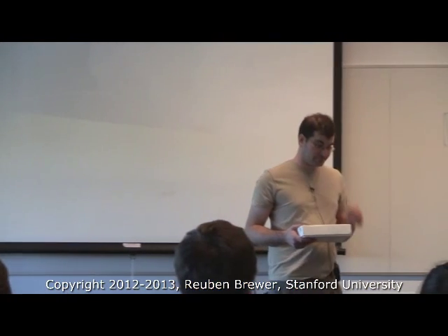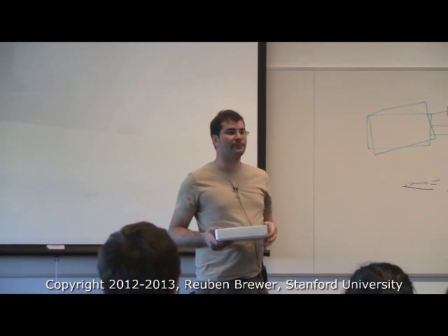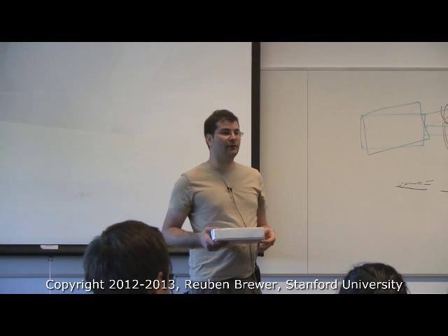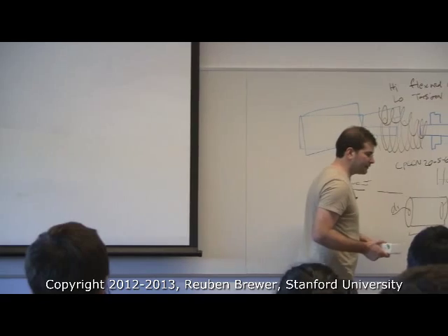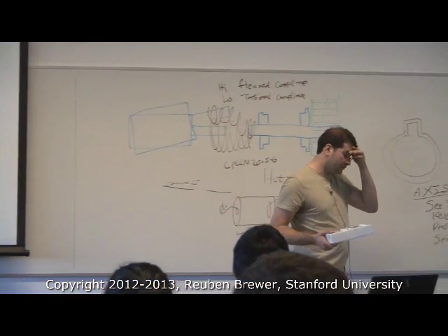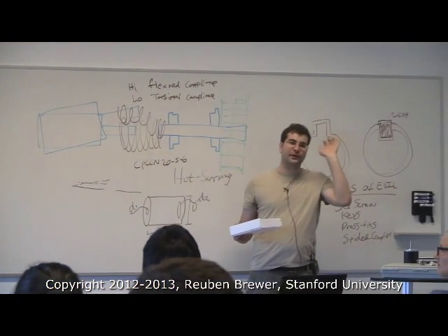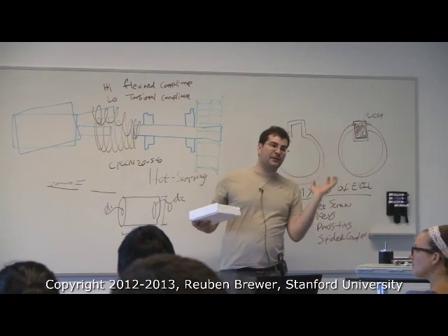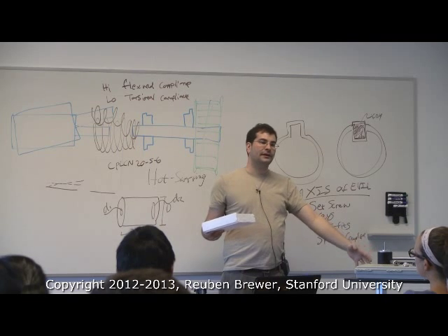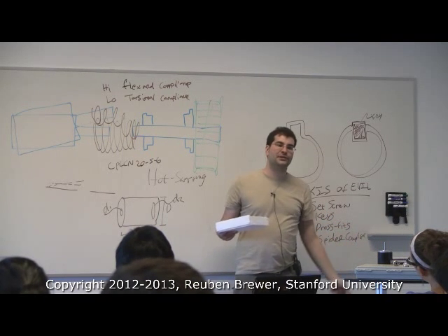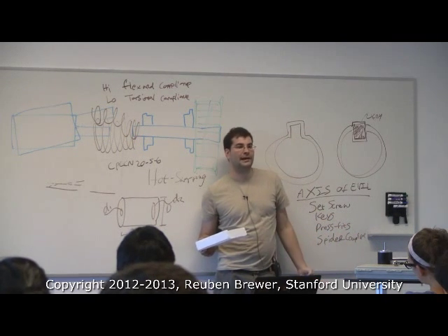So if I have like a 50 watt motor, it's in watts, right? And then you have some torque, how do you do this? So in your robot, you're going to know what you want to be doing, hopefully. So a scooter, you'll know you've got a fat guy like me going up a hill, and so the speed and the torque, okay, so now you've got the torque. And then you know what the gear ratio is, so you know the ultimate torque on that shaft.